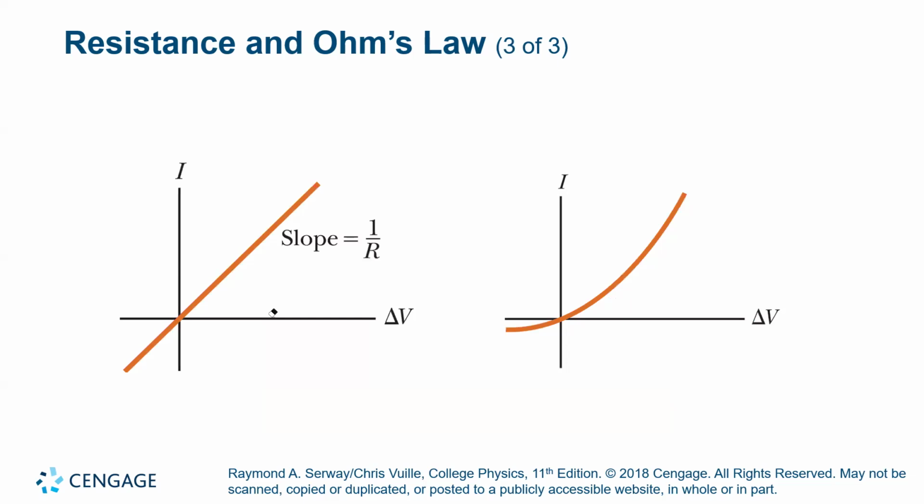And this slide illustrates the point I made before. Now notice I've changed the axes. I had voltage on the y-axis before. Now it's current. So if current is the y-axis, then the formula becomes I equals V over R. The slope now becomes 1 over R. Now it's very important to note that I write V because as an electrical engineer, this is the way we tend to write it, but it's always representing the change in V across 2 points.